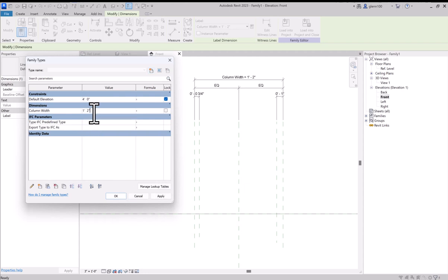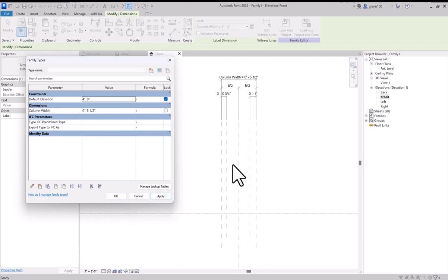Okay, so let's say we want it to be 5.5 inches wide. So 5.5 inches. I'm going to set that. I'm going to apply this. Okay, and notice that it moved these two in so that they're 5.5 inches and they're an equal distance from the center line here. Then also when it did that, because this was set to a permanent dimension, and the dimension was locked onto there, then when we move this, it also moved this line with it.